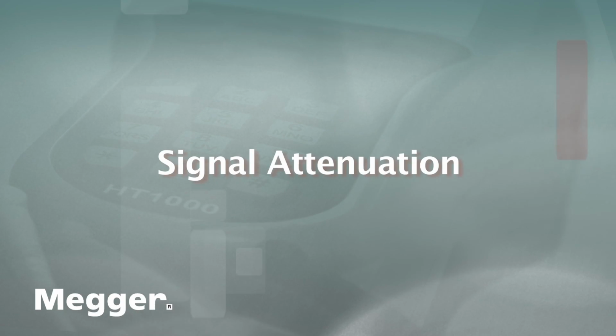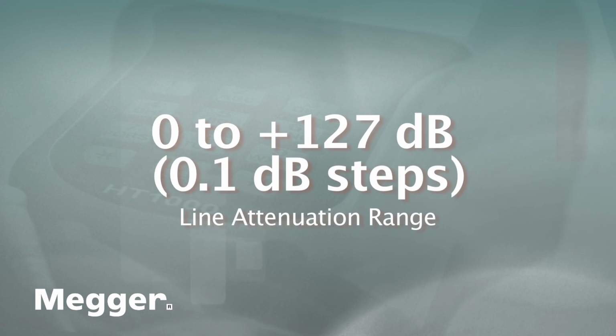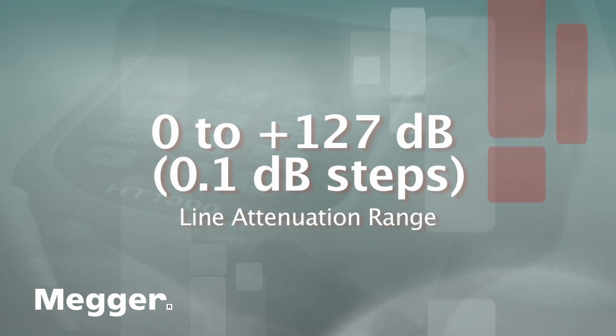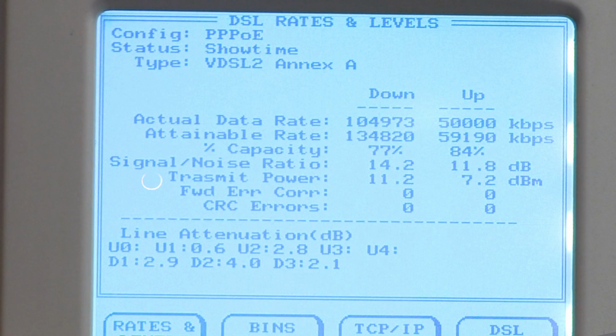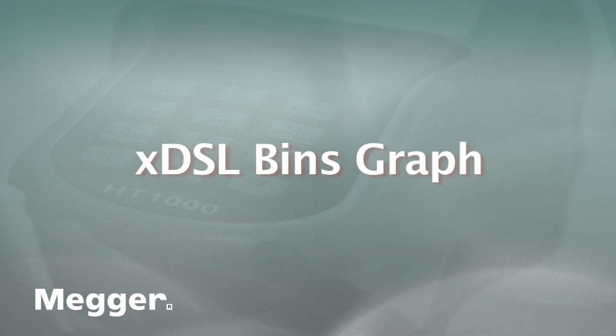Signal attenuation. The measured difference in total power transmitted and total power received over all subcarriers during showtime. Signal attenuation ranges from 0 to plus 127 dB with 0.1 dB steps. Transmit power. Value of the total output power of the modems measured in dBm.